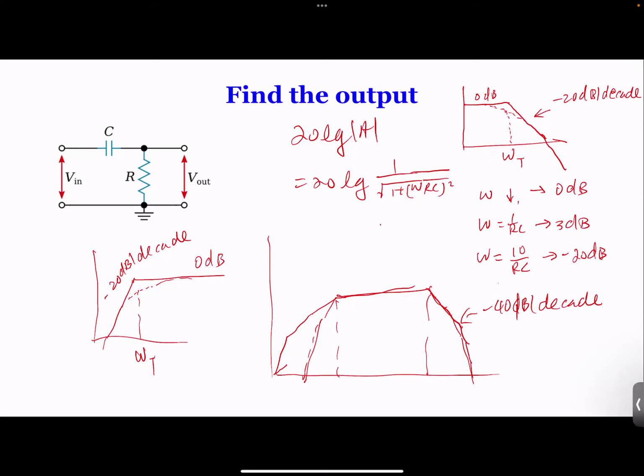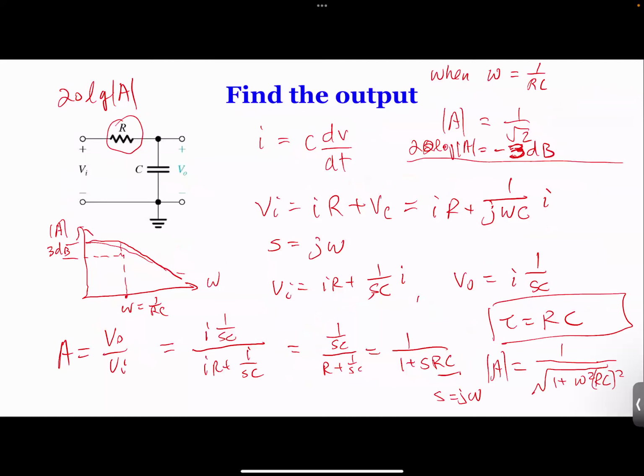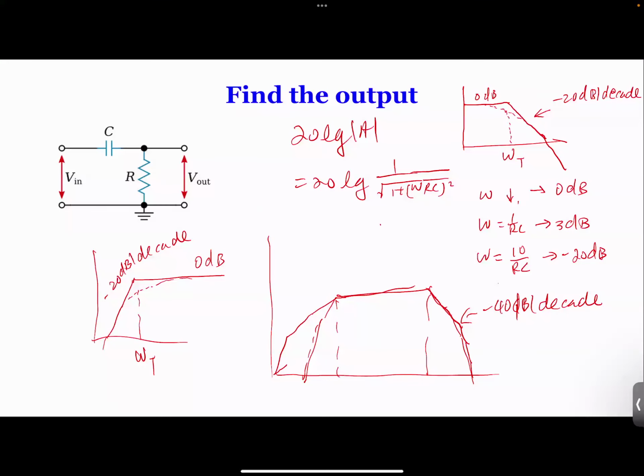And then we moved on to talk about the low frequency response, how the low frequency portion gets attenuated because the circuit is a CR circuit. The reason is always because the impedance of C is 1 over omega C. In the previous circuit, when omega is big, 1 over omega C becomes 0, and your output becomes 0. So that's why the high frequency gets attenuated. When the frequency gets to a certain point, you don't have any output.